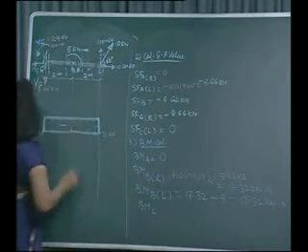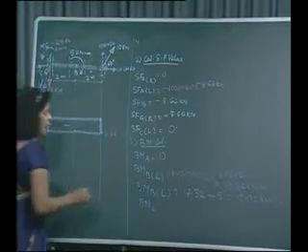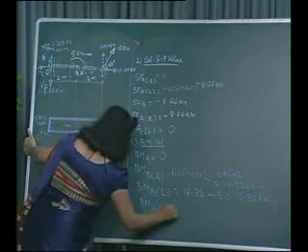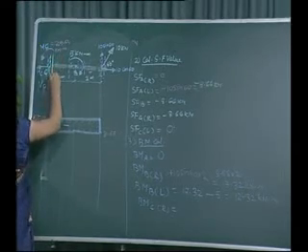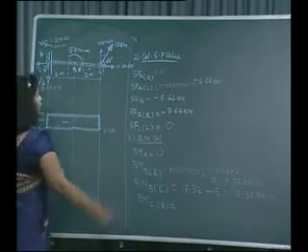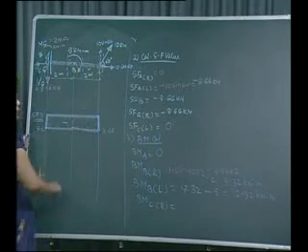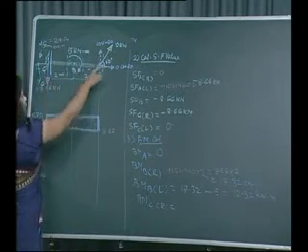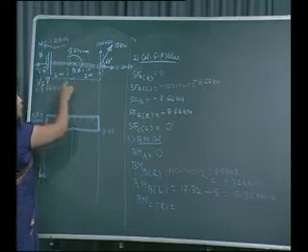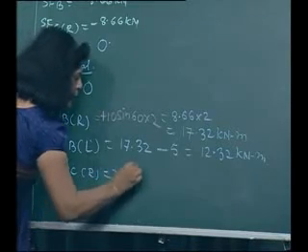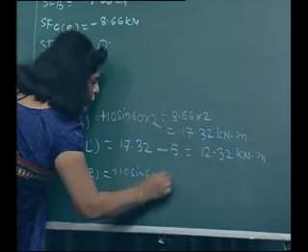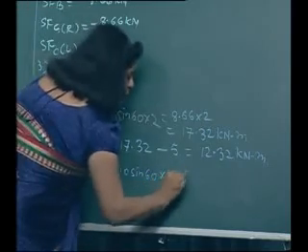And bending moment at point C. Now C is also having a couple, right? So I have to calculate just right and just left. So this is just right of the couple. So how many forces are there? One force and one couple. What is the distance up to point C? 2 plus 2, that is 4. So plus 10 sin 60 into 4, and second is the couple, that is 5.